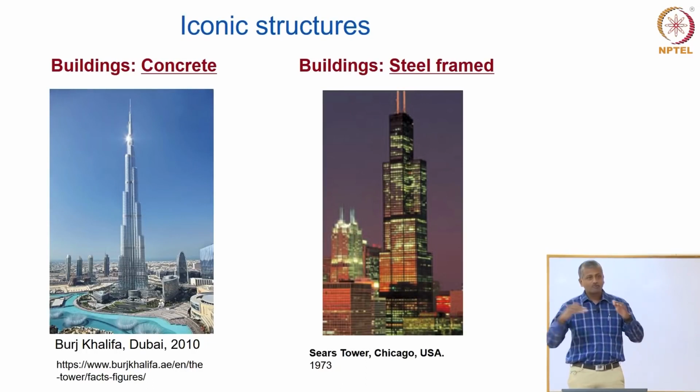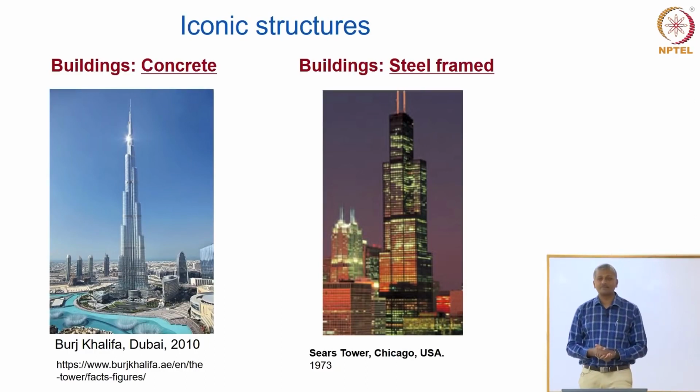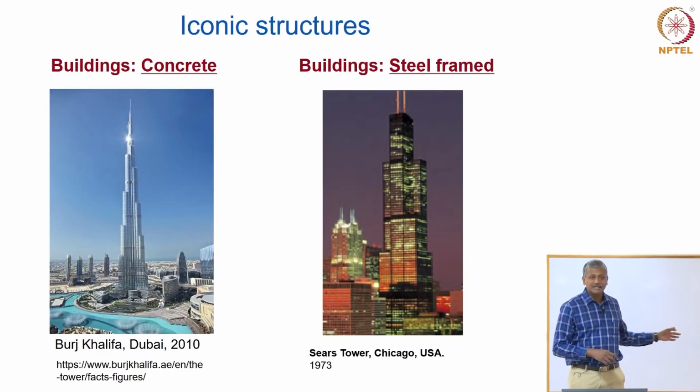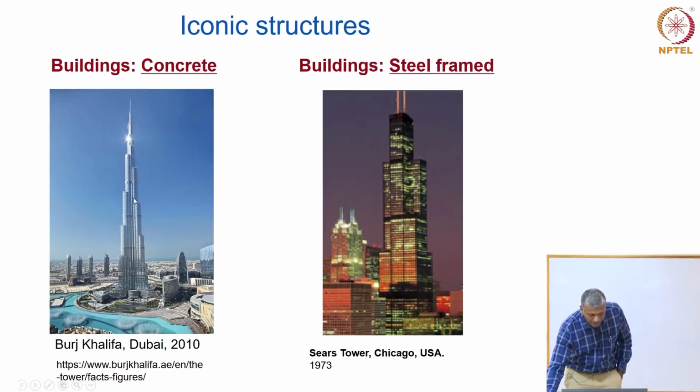So when one floor gave way, the rest of them simply collapsed. Progressive collapse is something that they did not actually design for in the World Trade Center buildings. But as far as Burj Khalifa is concerned, even that has been taken into account, okay. So if a progressive collapse happens, for example, at this level here, the structure may collapse, but it will stop collapsing at this point here.